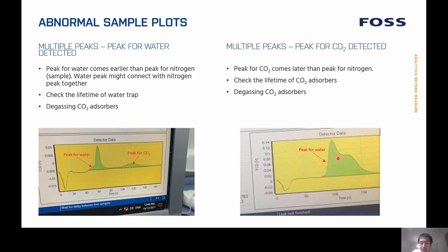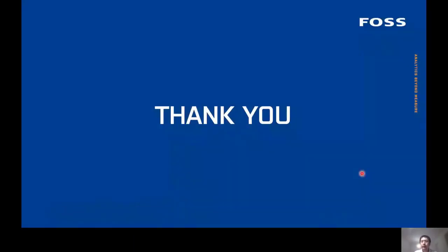So you should check the CO2 trap lifetime. You have to do the degassing, as I also mentioned. If you have a small CO2 trap, that usually means the CO2 is not completely absorbed. You should check the CO2 trap lifetime. So this is all the information I want to share with you, and thank you for joining this session.